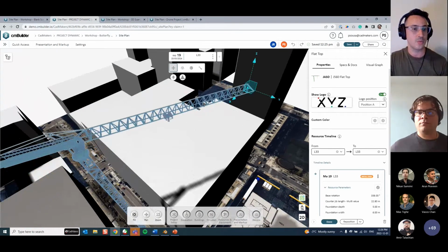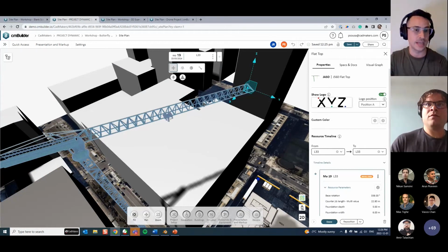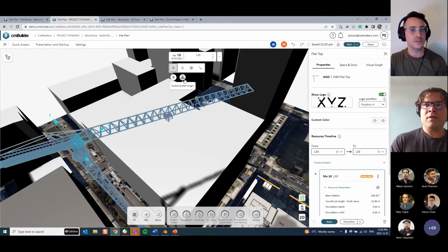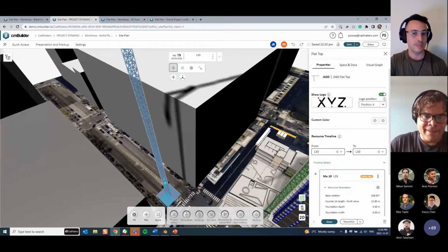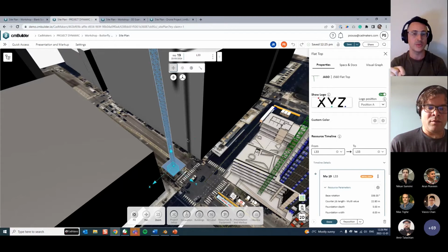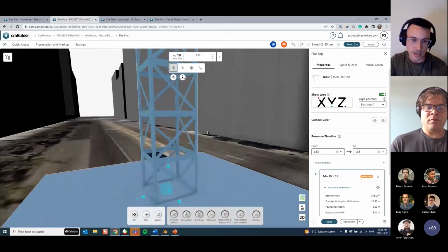This is the default behavior, where you are defining a local positioning for these handles, right? But over here in the bottom, we have a part origin. If you switch this to part origin, these handles will go and find the part origin. For resources that are in our library, the part origin is defined by us, and it's usually at the bottom of the resource, because that's also the 000 that we use to place the resource on the ground, right? In this crane, the part origin is at the bottom of the mast, right?